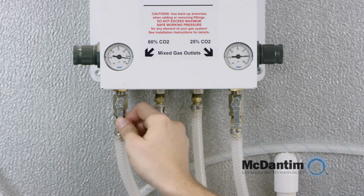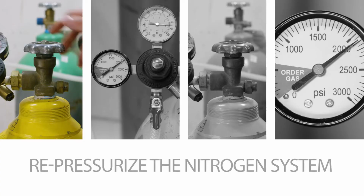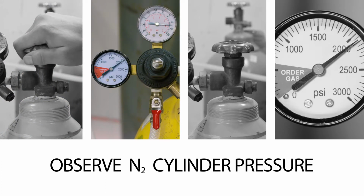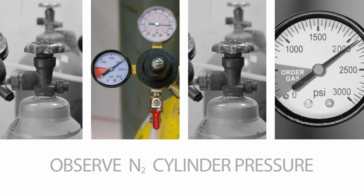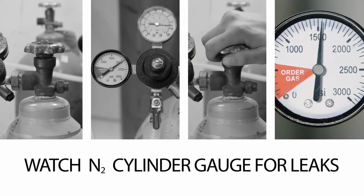Start with closing the left ball valve on the left side of the blender and repeat the previous 4 steps. By doing this, we are specifically testing the right side mixed gas line of the blender and the secondary regulators and keg couplers downstream.